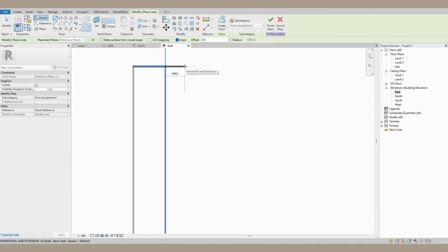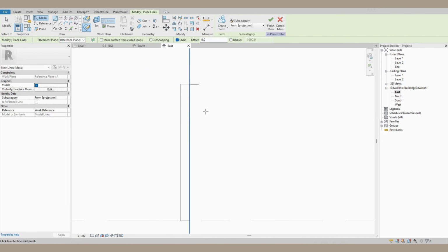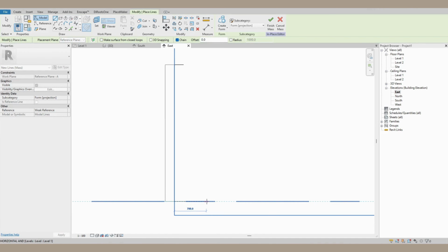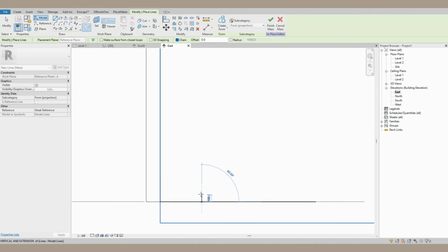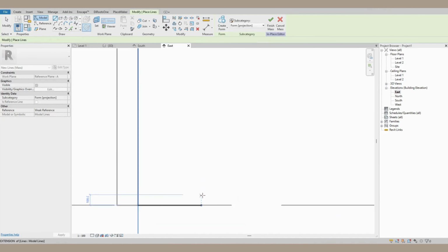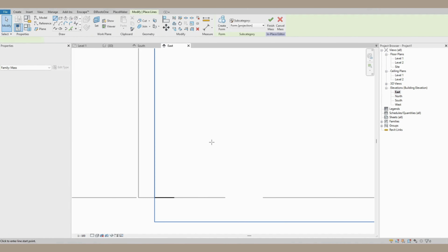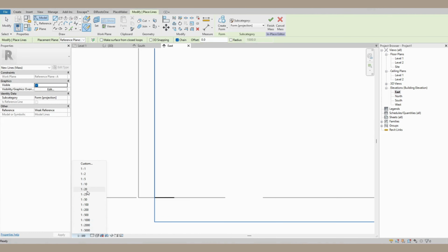Just at the top, we're going to make sure that our line is about 200 millimeters offset. So I normally like to make my benches around 600 or 580 deep. We're thinking this is probably going to be a waiting area bench. It's not really going to need that much comfortability, I would say. And then we're going to go for it.